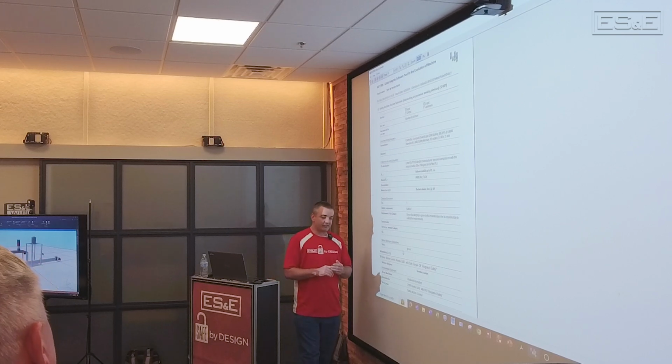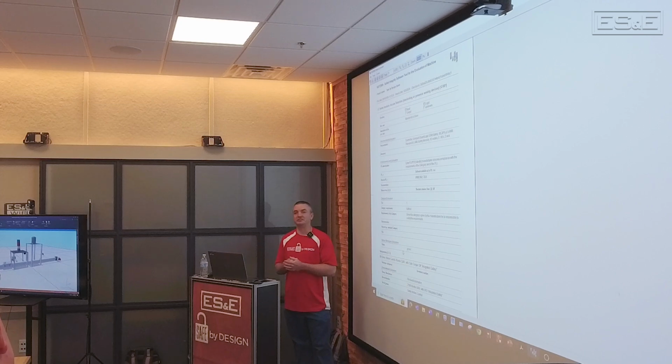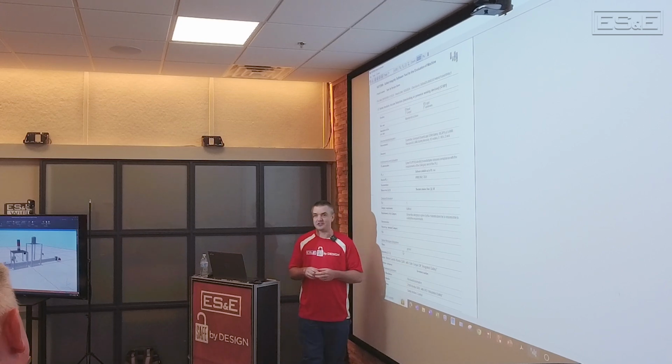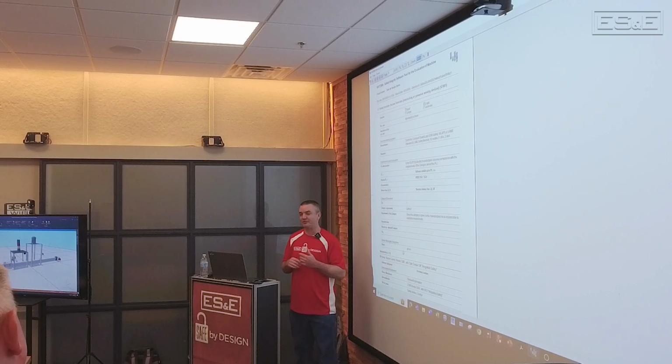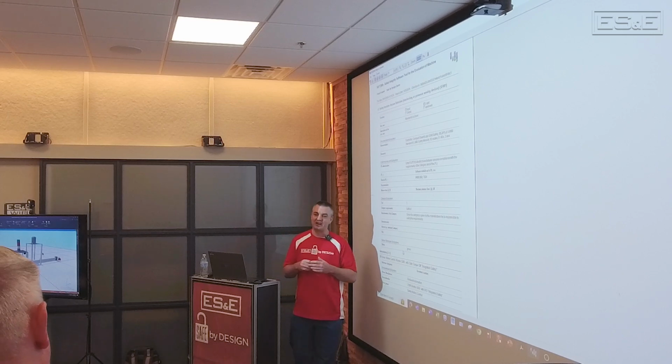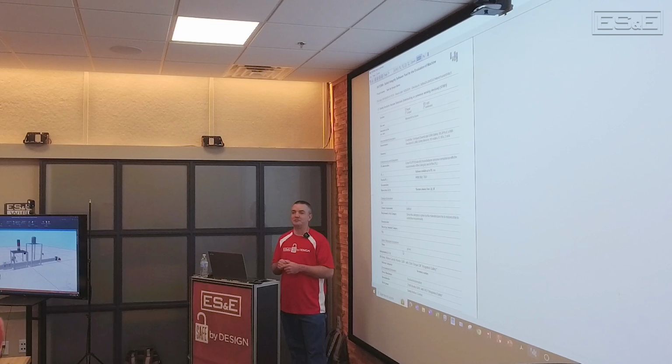Yeah, and definitely when you do the risk assessment portion, they recommend it being a team-based approach, and the standards actually kind of recommend that or call that out. Not just your controls engineer that's working on the machine. Try to get multiple people involved, maybe someone from the front office, administrative level. HR maybe? HR, someone that's not likely working on that machine, just so that they're not likely to overlook a hazard or something like that they see. Okay. More to question it.